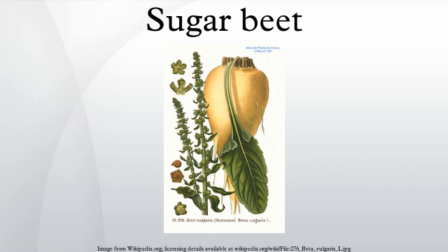Before entering the next stage, the thin juice may receive soda ash to modify the pH and sulfitation with a sulfur-based compound to reduce color formation due to decomposition of monosaccharides under heat. Evaporation. The thin juice is concentrated via multiple effect evaporation to make a thick juice, roughly 60% sucrose by weight and similar in appearance to pancake syrup.